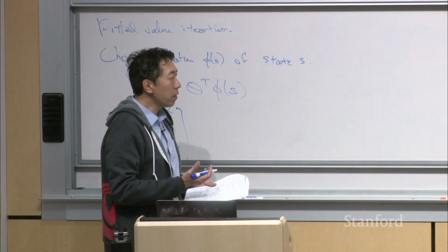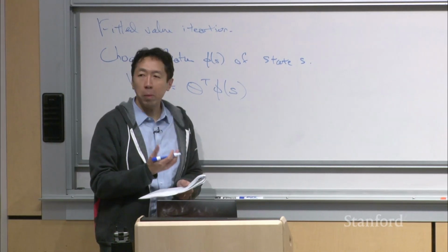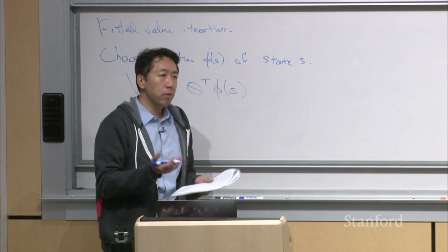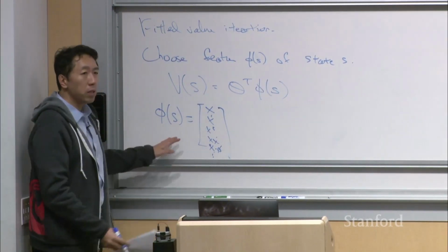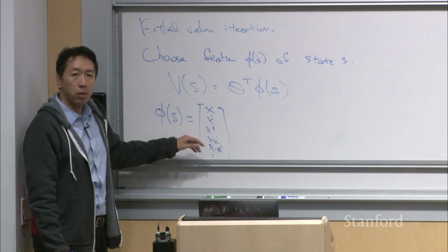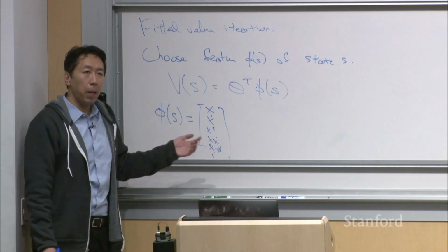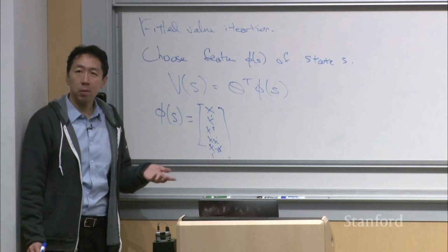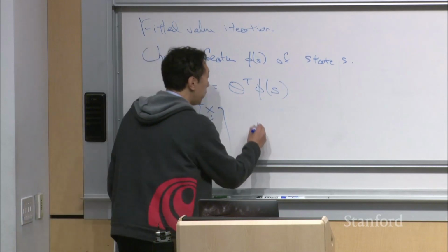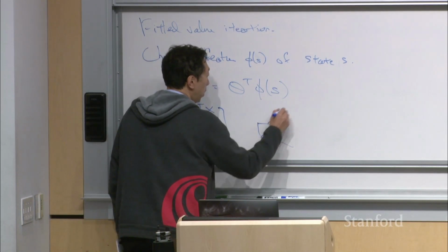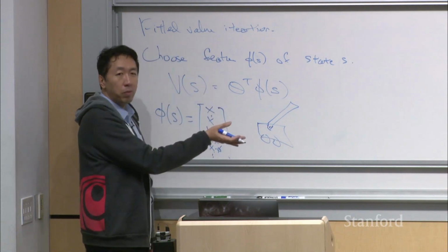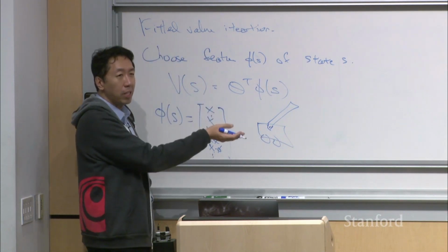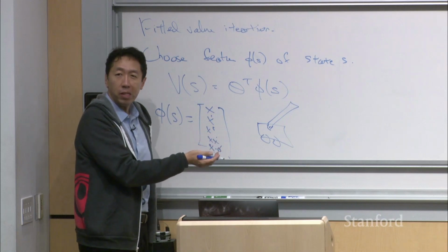So the value function captures if your robot starts off in this state, how well is it going to do if it starts here? So when you're designing features, pick a bunch of features that you think help convey how well your robot is doing. Does that make sense? And so maybe for the inverted pendulum, for example, if the pole is way over to the right, then maybe the pole will fall over. Or give it a reward of -1 when the pole falls over, right?